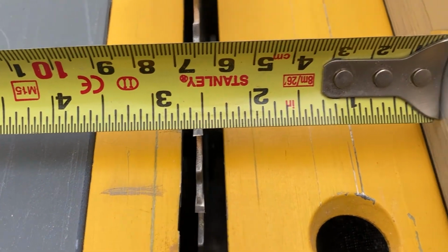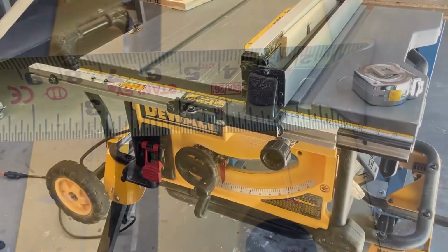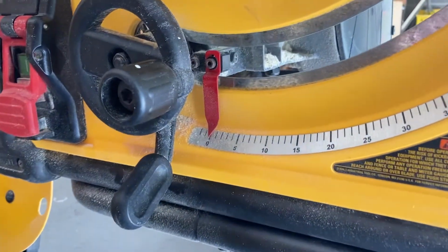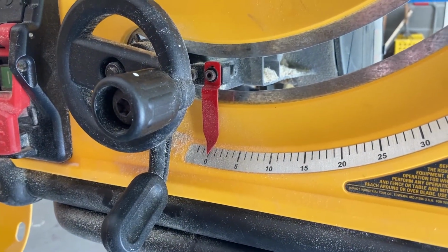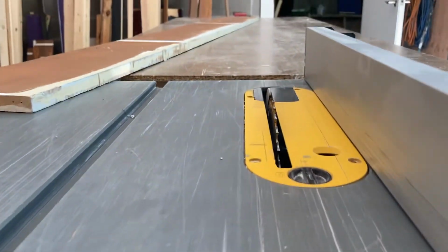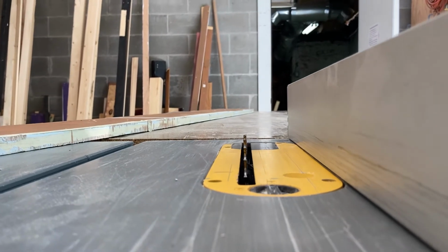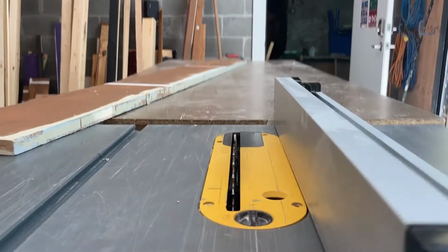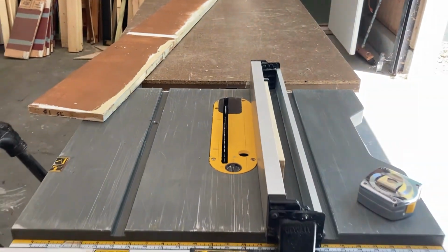That's pretty much perfect. So we don't need to do any angular or bevel cuts on this particular saw for this project, but it's always a good idea to double check that the blade has been left perpendicular to the surface. So you want to really kind of eyeball it and make certain that it's 90 degrees to the surface of the table. There's no angle that's been set in it by someone previous to you using it.